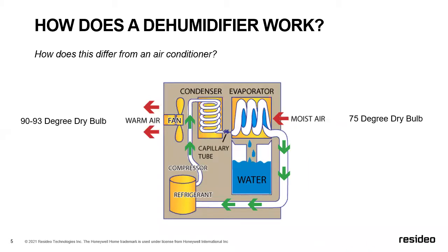So in the world of air conditioning, we're about sensible heat and latent heat, two types of loads that we tend to have to manage in a home. The sensible is the dry heat that we're trying to then cool and deliver conditioned air into the space. And when we cool air, the byproduct of that is we have moisture removal. As air is cooled, it's holding moisture. We're going to remove that, but the ratio in our HVAC equipment today, the sensible ratio is typically a little higher than what we can do from a latent load. So a lot of times in a high humid environment, we may need another appliance, whole house dehumidifier that we're seeing here, that serves its primary function as removing moisture.